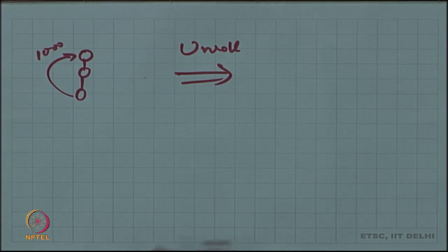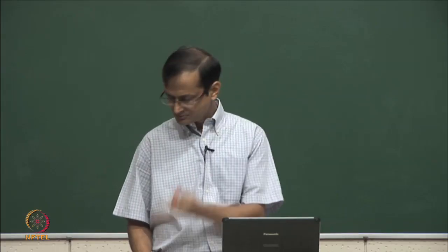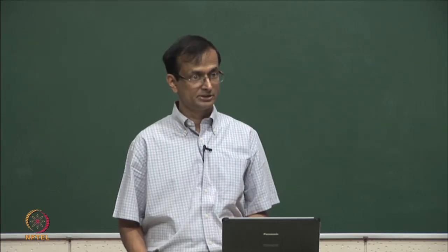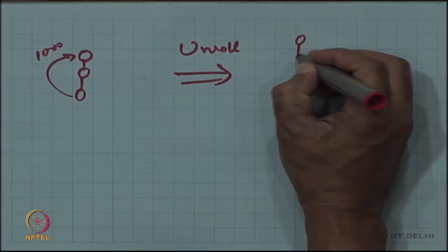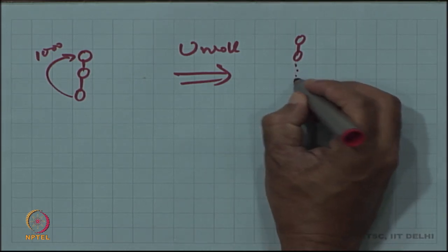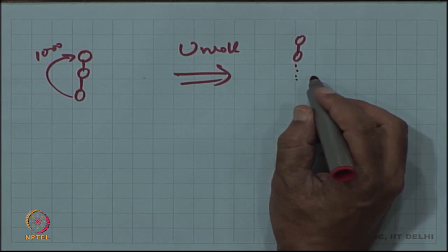Now, it is possible that because of the unrolling, you do not need 3000 cycles, because there is some parallelism out there. Perhaps you are able to do this in 2000 cycles. You are still limited by resources that are available, but perhaps it is 2000 cycles. But what does that translate to in terms of the FSM? It gets that long. That is what it becomes, at least by default, unless you do something about it.